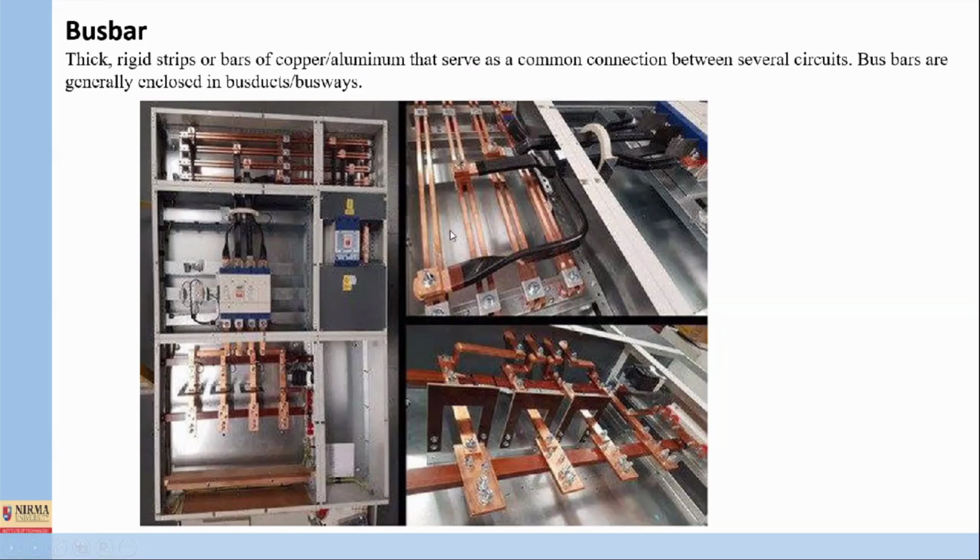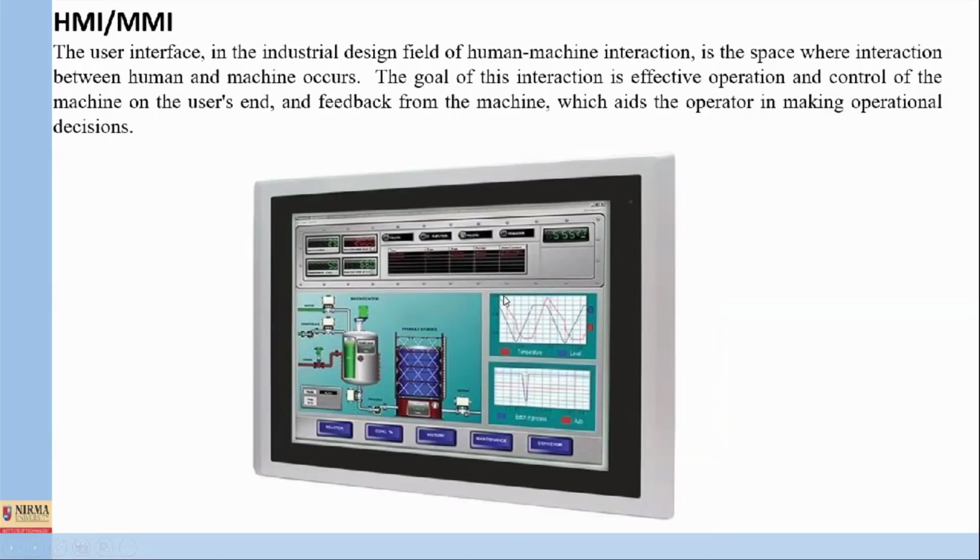You can comfortably fix the supply, and there will be no sparking or loose connection, so no arc formation and no air ionization if we go for this firm type of connection. That's why we require the bus bar arrangement, over which the conductors are directly mounted.